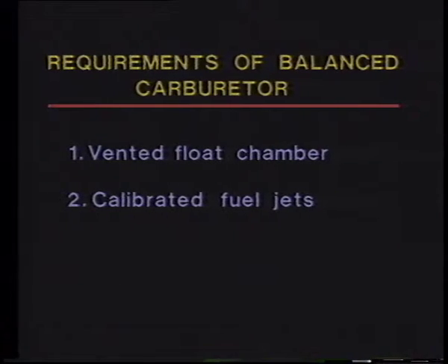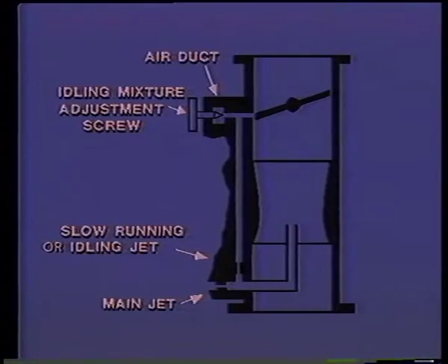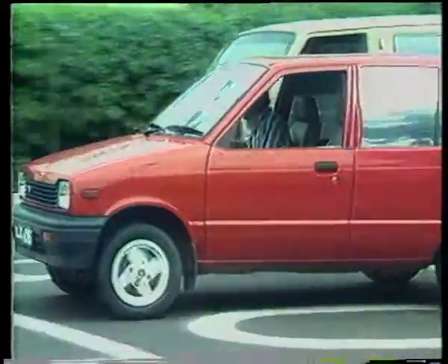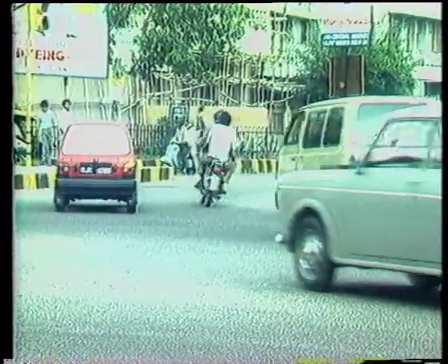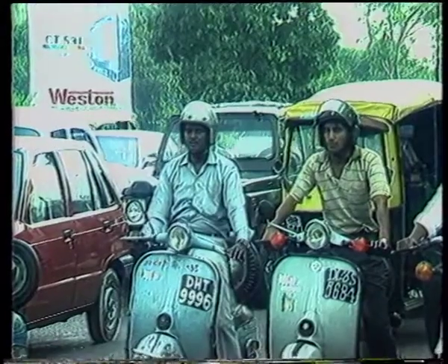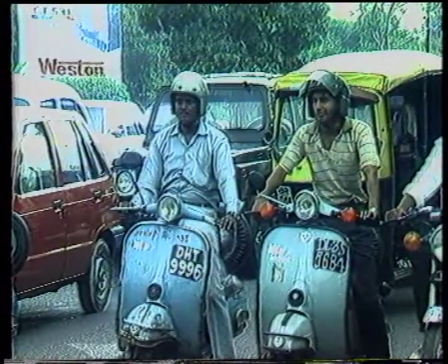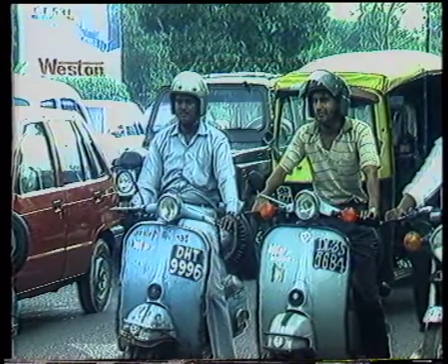Very simple carburetors have only two jets, one the main jet and two the idling jet. More jets can be incorporated for operation at maximum power, cruising, slow running, and for acceleration. During idling, the throttle will be almost completely closed, so the velocity of the airflow through the venturi will be too low to develop depression sufficient to draw off any fuel through the main jet.